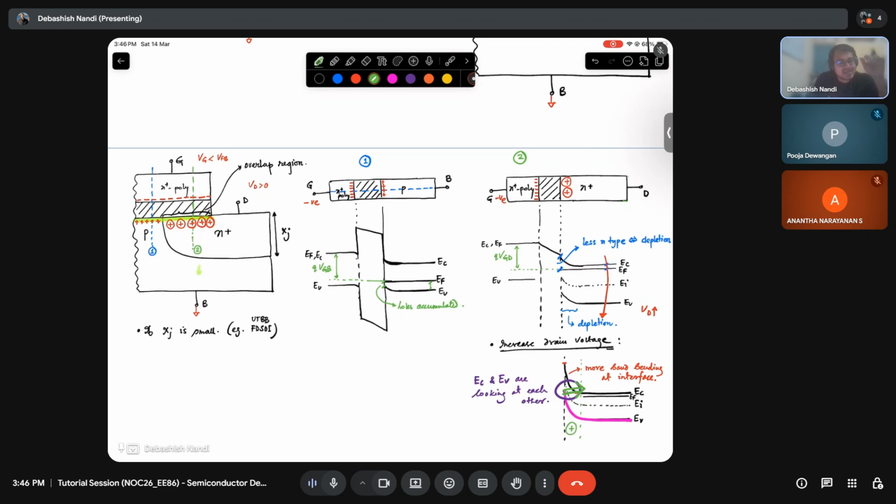So inside the depletion region, from EV, electrons are tunneling through that depletion region towards the conduction band, where they can carry current. In the valence band, electrons cannot carry current, right? But in the conduction band, electrons can carry current. And this leaves behind holes here and electrons here. Tell me if you have understood this much.